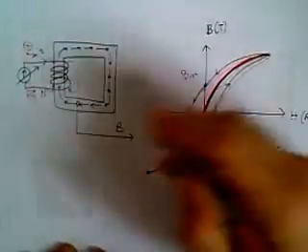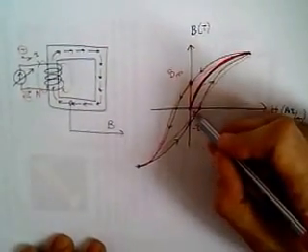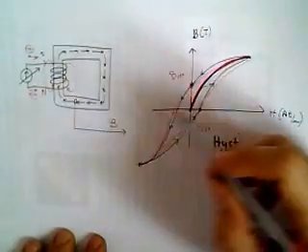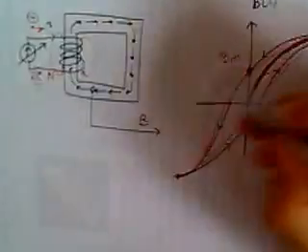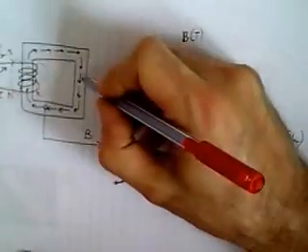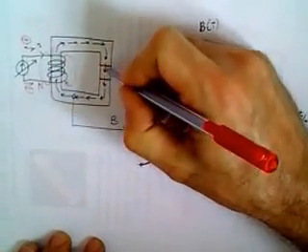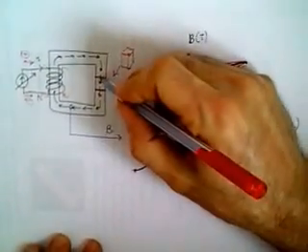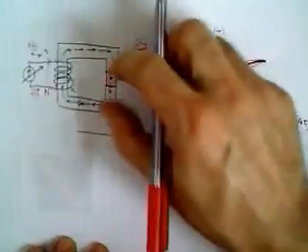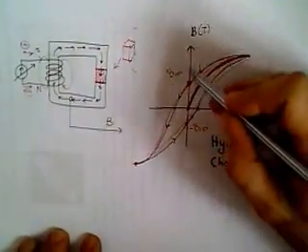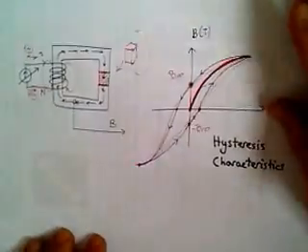For ferromagnetic materials, at this point, we just introduce a magnetic field and return to the zero condition. So the magnetic flux density remains. That means we can magnetize a material. We can produce magnets. That's the production technique. Inside the circuit, there is a gap, and we insert a material in here, increase the current, take the material out, and this becomes our permanent magnet. So permanent magnet production is performed simply with this structure.